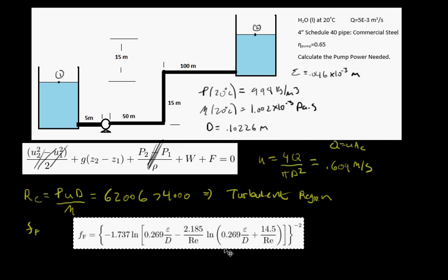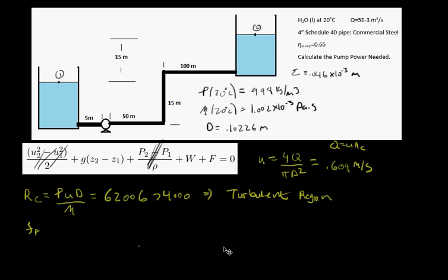So I just went ahead and used that program on my calculator to calculate the Fanning friction factor. It's a little bit more accurate to do it that way, and also it's quite a bit faster. So my program told me that the Fanning friction factor was 0.0054.